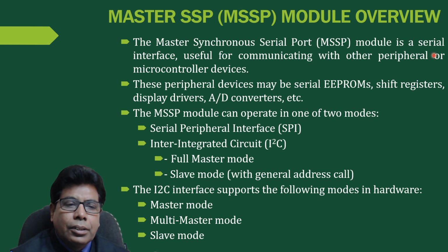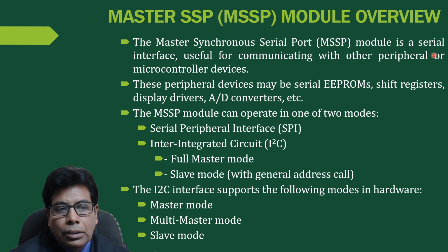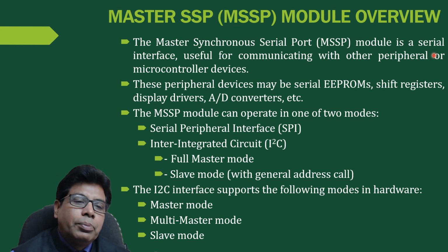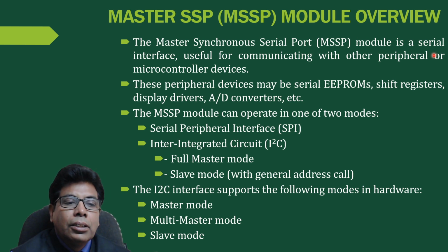Then the MSSP module can operate in one of the two modes: serial peripheral interface, that is the SPI mode, and the inter-integrated circuit I2C. So in I2C mode, it has full master mode and there is a slave mode. Now already we have discussed the serial peripheral interface mode for this MSSP.